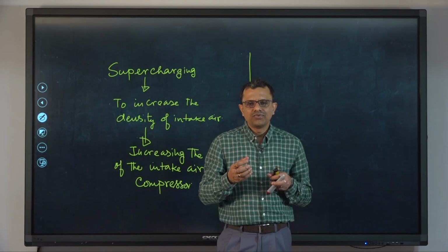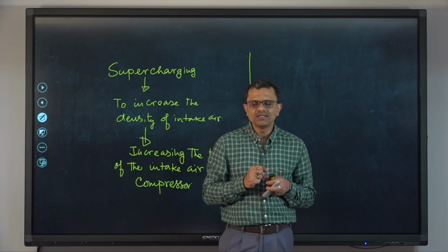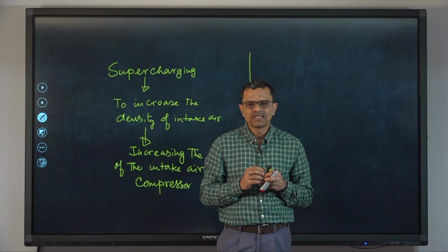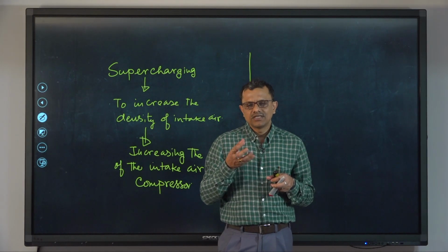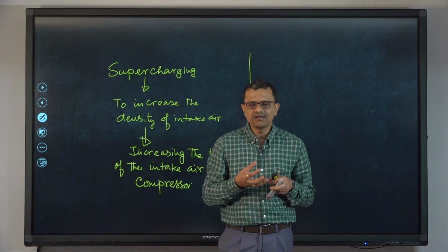So, we need one compressor to increase the pressure of the intake air, and to run the compressor again we need to supply some amount of energy in the form of work, and that energy should be borrowed from the engine itself.